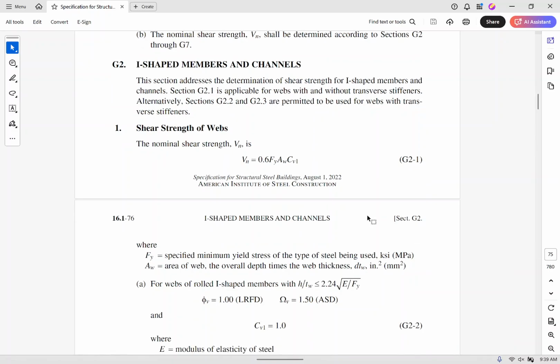Do you remember that video I showed you of the plate buckling, the shear plate buckling? What if I told you that after it buckled, you could keep loading it, and it would actually still keep resisting load? Let's take the image here on the board. You load this, it buckles, and so you have this buckled zone right here. This is sort of where the buckle is. Well, if you keep loading it, this section of steel right here is